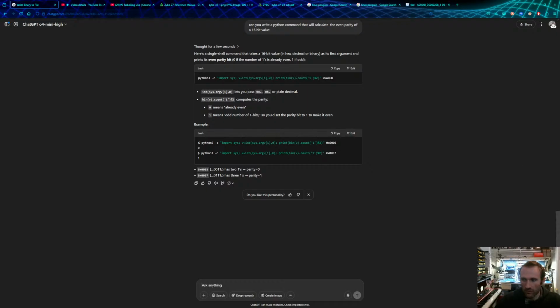All right, so parity is a way, I think, to understand data integrity, the data that you're sending over. So I'm assuming that the encoder expects to have some parity bit that's set, and it looks like this Arduino library is setting some parity.